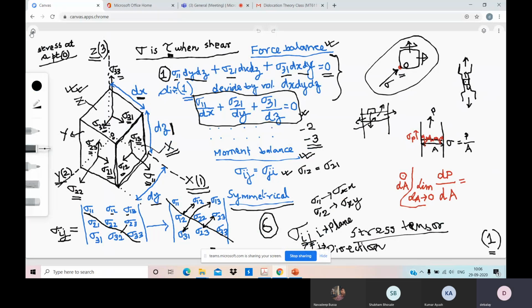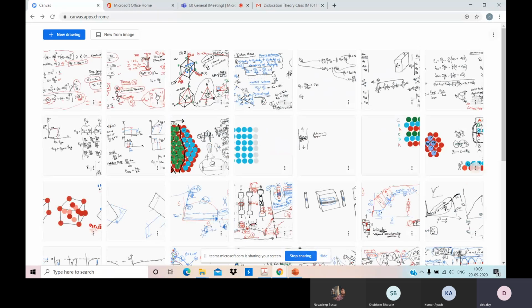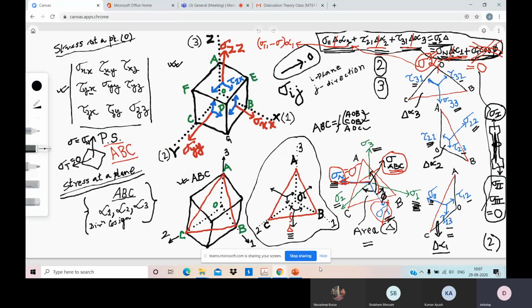Then in the next discussion, we have covered that we try to derive the resultant stress acting on any arbitrary inclined plane, because plane number 1, 2, 3 or xyz are basically my face planes of the parallelepiped, 3-dimensional body.